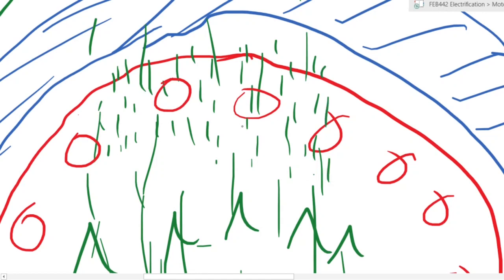If you look at these copper bars from the perspective of the copper bars themselves, you have a copper bar which is mounted inside here, and from the point of view of that copper bar, it is experiencing a magnetic field that is moving in a certain direction. Because this is a rotating magnetic field, it is like the field is cutting across the windings, or the bars themselves.